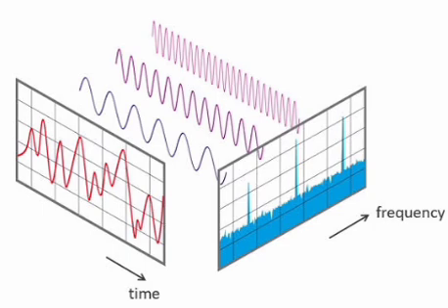Right shift: x[n-1] has Z transform z^(-1) X(z) plus x[-1]. x[n-2] has Z transform z^(-2) X(z) plus z^(-1) x[-1] plus x[-2]. First difference: x[n] minus x[n-1] corresponds to (1 minus z^(-1)) X(z). Conjugation: x conjugate of n corresponds to X conjugate of z conjugate.